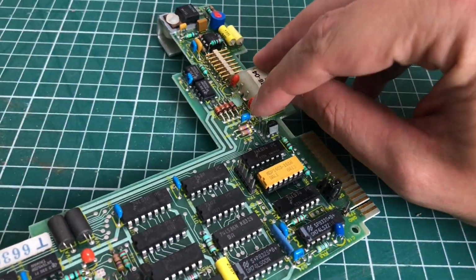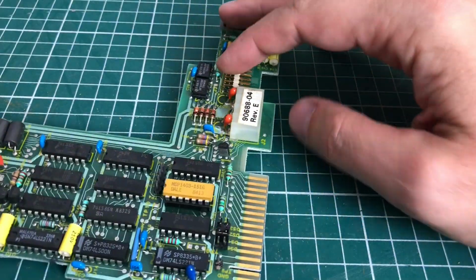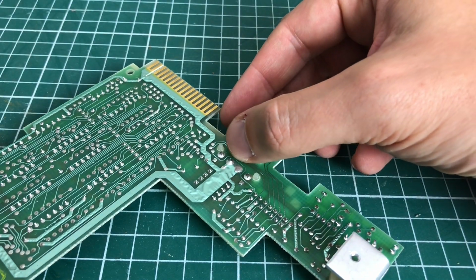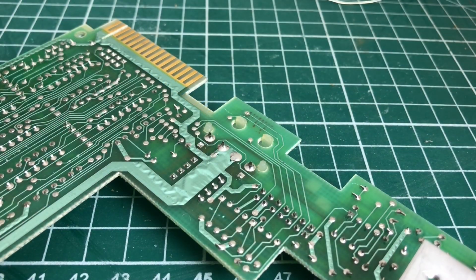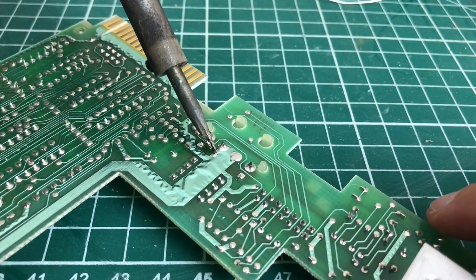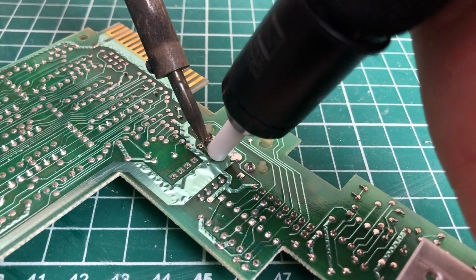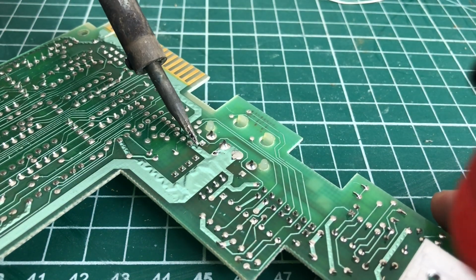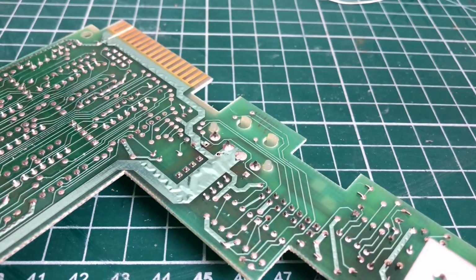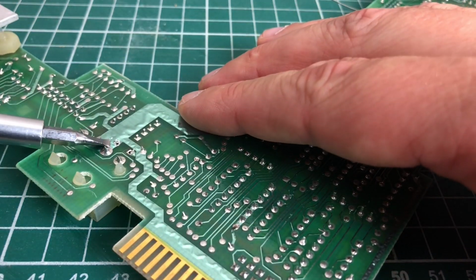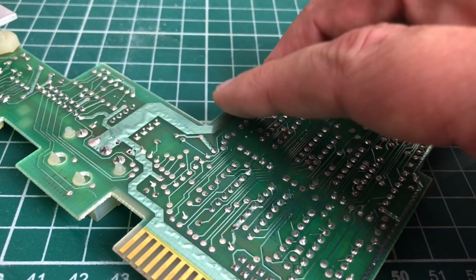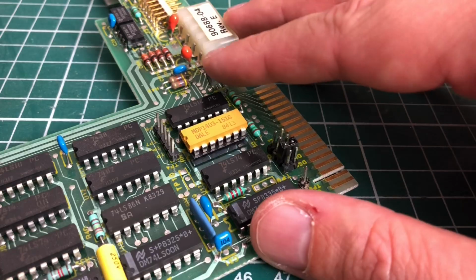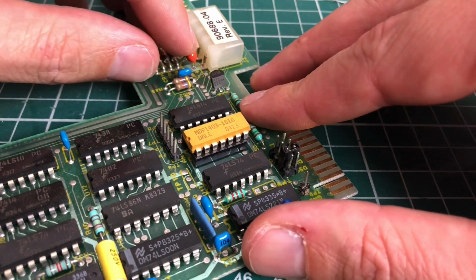So here on the power connector we have two tantalum capacitors, and we have already determined that one of them has gone short circuit. Or at least that's what I thought. So I decided to just blindly go ahead and desolder the capacitor which I thought was faulty. I used my desoldering tool to remove all of the excess solder, and bent the pins up straight so that I could easily remove the capacitor from the printed circuit board, hoping that that would remove the short also.